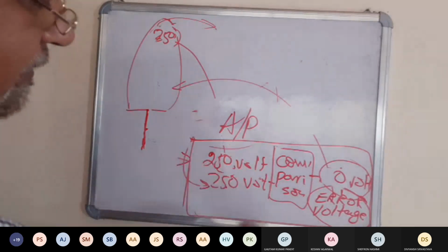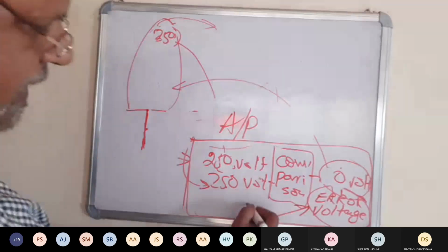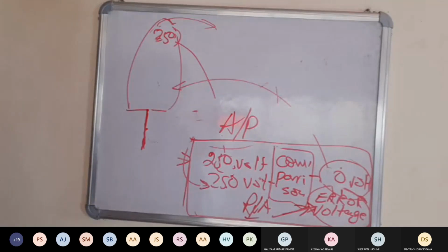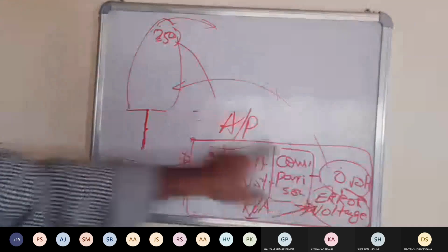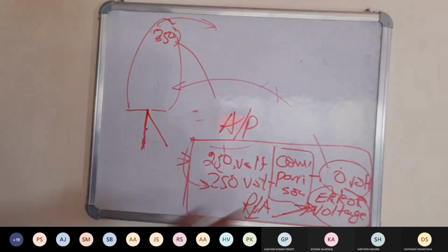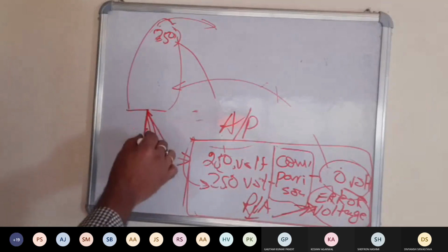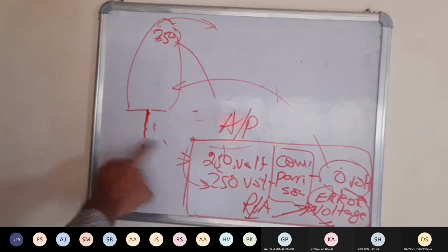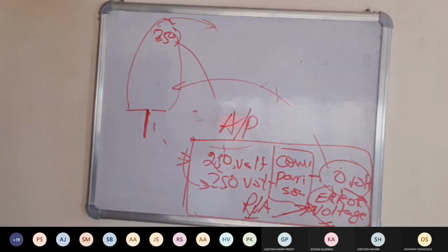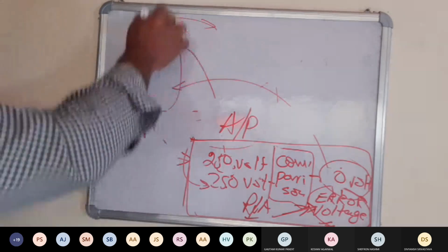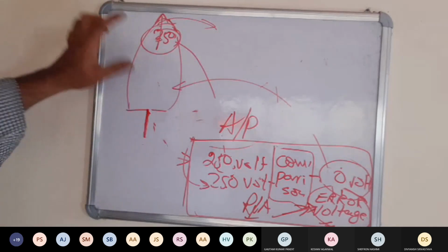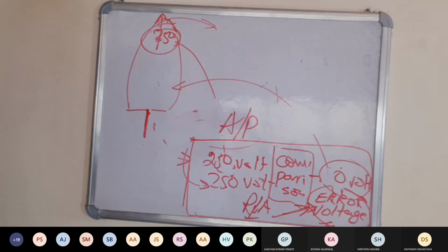Of course, what we did not discuss to simplify is that there is also a rudder angle indicator, and its input also goes in. So from the final combination of these three, it is found out how much rudder to give. As the error reduces, the rudder also reduces. When the error becomes 0, the rudder will be midship. And so now the vessel will steer on this. It is not so simple. There is more to it, but we will see in the next class.